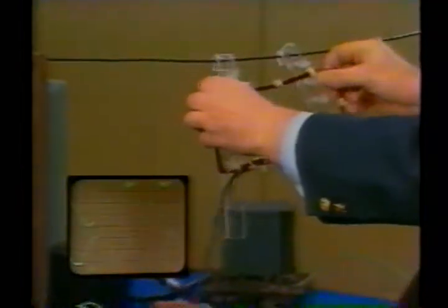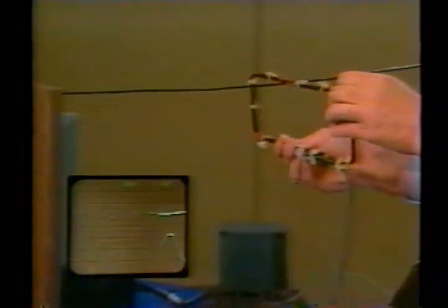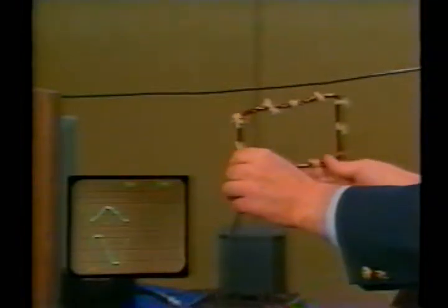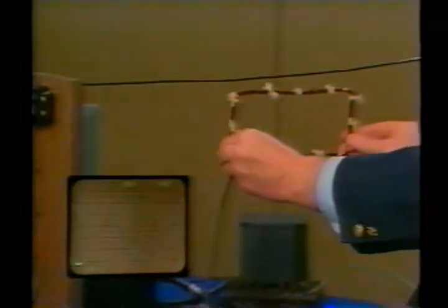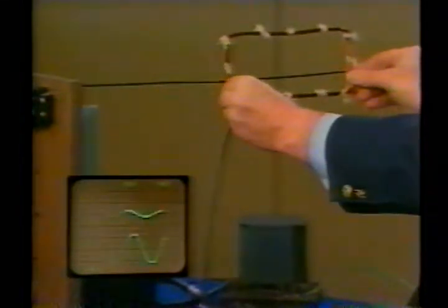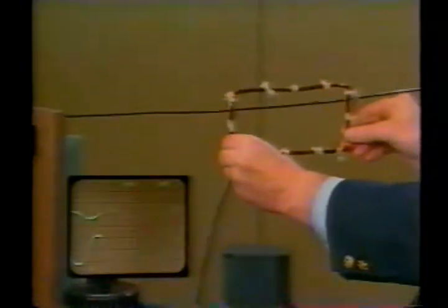With the coil straddling the wire, the flux passing through the coil in the upper section is oppositely directed to the flux through the lower section. With it symmetrically positioned, the net flux is 0, so the measured voltage is 0. The scope traces are triggered on the wire current, the lower trace, so we can see the change in phase as the coil is moved from below the wire to above the wire.